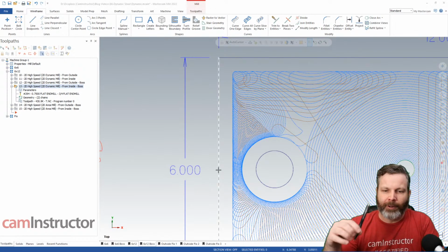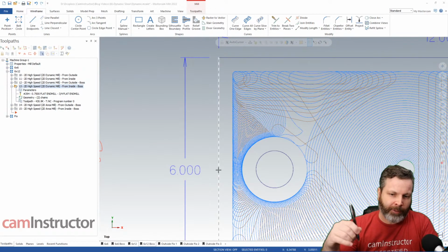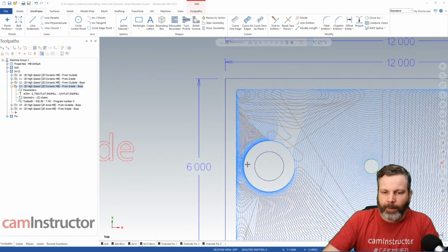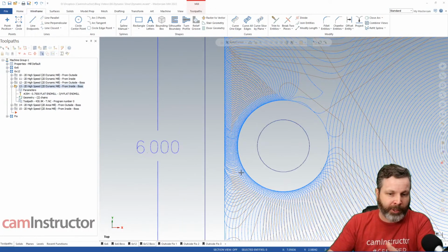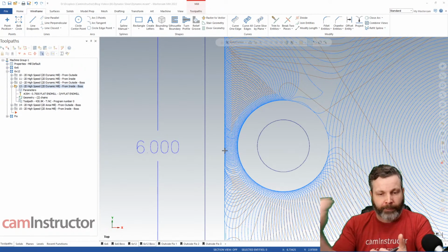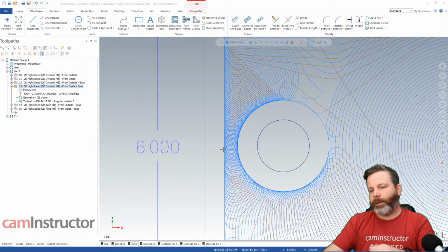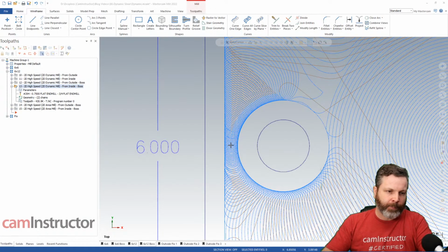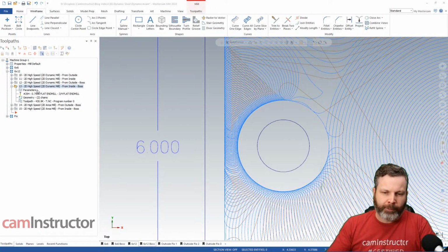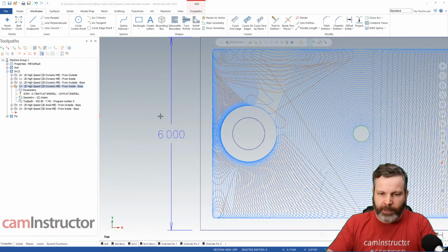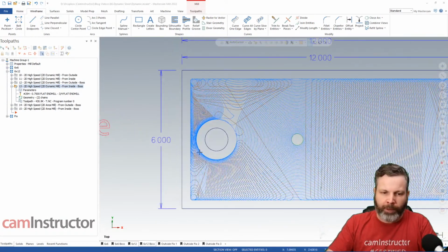if our cutter at 100 inches per minute is right on the border of breaking, and the equivalent to 100 inches per minute inside this section of the toolpath is 30 inches per minute, and we're feeding at 3 times that, we can have a problem. Okay, so how do we go about addressing that? There's no feed rate override inside Dynamic, so there's no switch that we can turn on to fix that, but we'll have to address it.